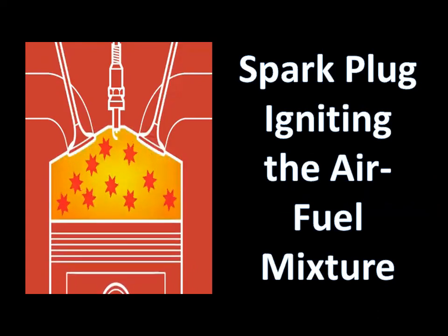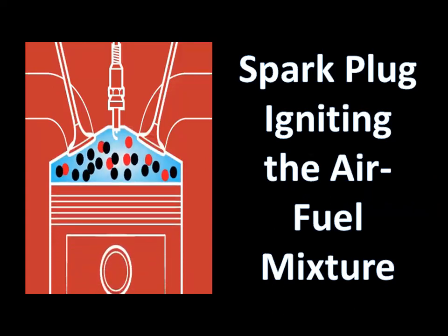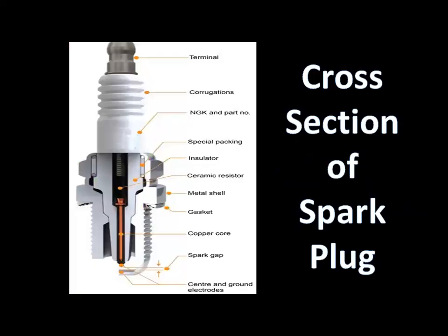The spark at the plug electrodes ignites the compressed air fuel mixture in the combustion chamber. A spark plug is contained in a metal shell, and the lower end of the shell has threads that match the threads in the cylinder head spark plug opening. A metal center electrode is positioned in the center of the spark plug, and a ceramic insulator surrounds this electrode. The center electrode and insulator assembly is mounted in the metal shell. The upper end of the shell is crimped over the insulator, preventing cylinder pressure from leaking up through the spark plug.